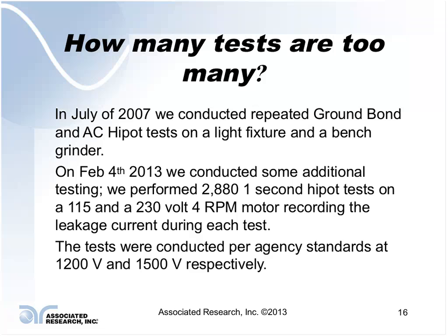So this bench grinder was a nice little tool because I could crank up the motor on it and you could actually see the product run, the light fixture on the grinder itself would light up. And we would go through and do Hipot and ground bond test on it.